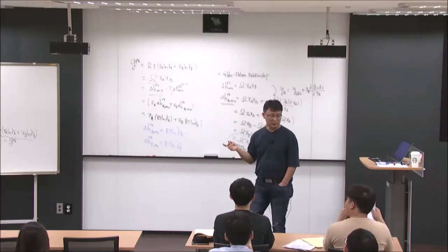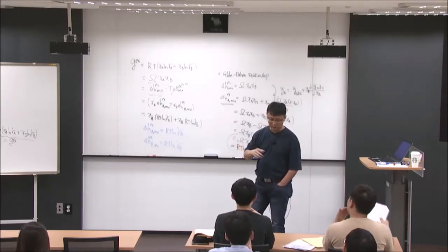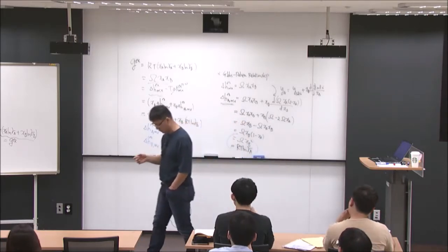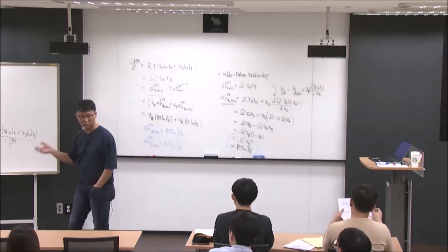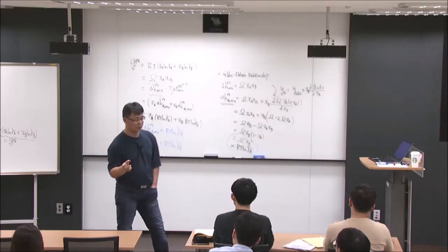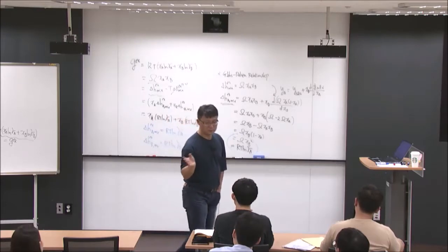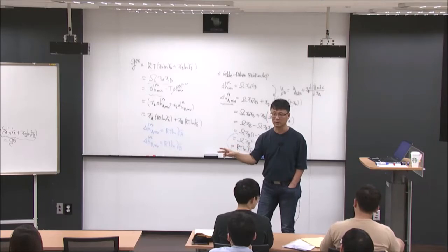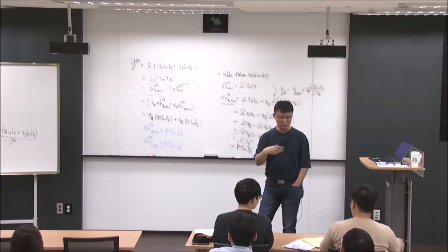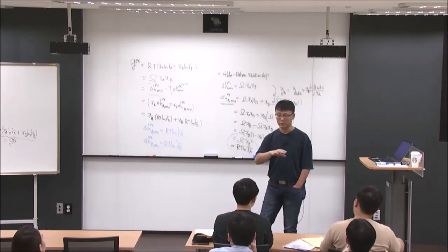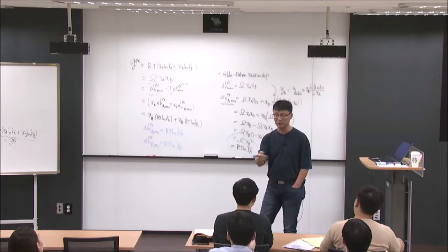And then we try to expand this solution thermodynamics a little bit further to the ideal solution, the regular solution, and the real solution. So the ideal solution assumes that the activity coefficient is 1. So the activity coefficient is not changing with composition or temperature. It's always 1. It means when you add a new component to the given solution, that component has almost no interaction with the existing components in the solution.